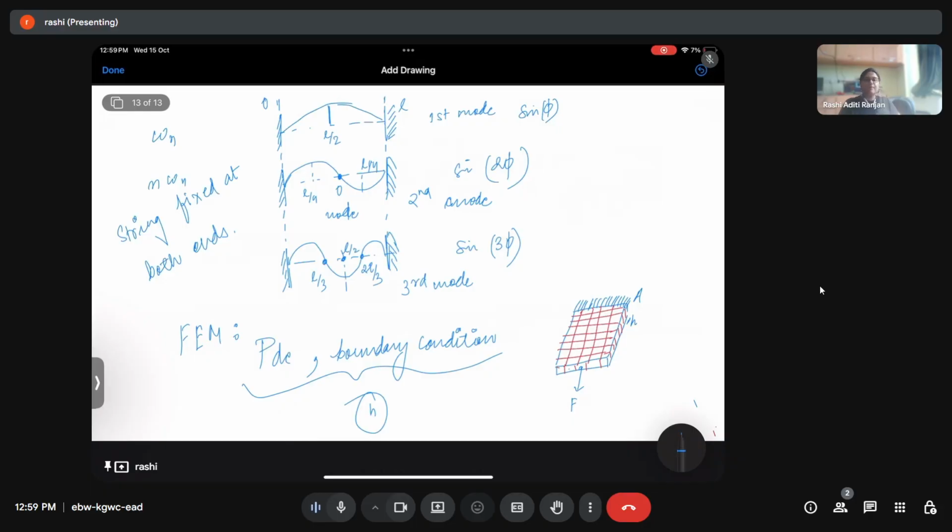And it is generally preferable that after solving this kind of simulation, we try to validate the model. We create the same kind of setup, apply a force, and see how it practically moves. Then we validate our FEM analysis with this. And then we know that our FEM analysis and the mesh size that we have generated for the system is good to go for a good solution. And then we can further analyze it.